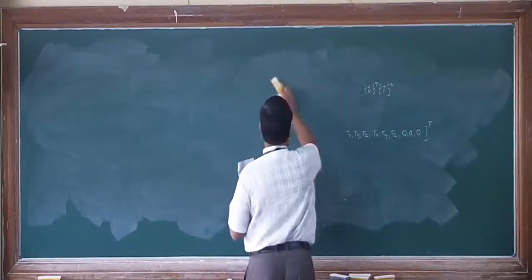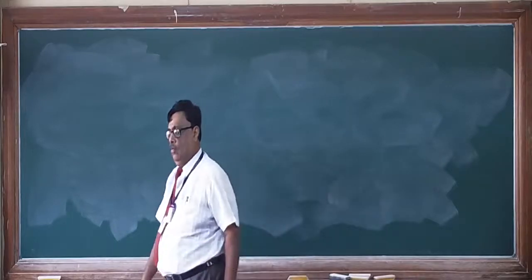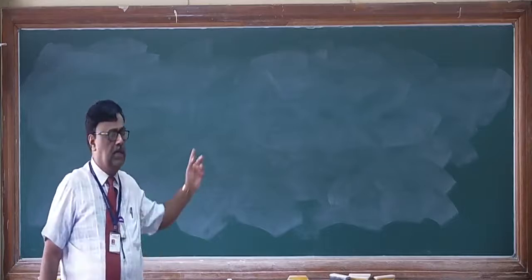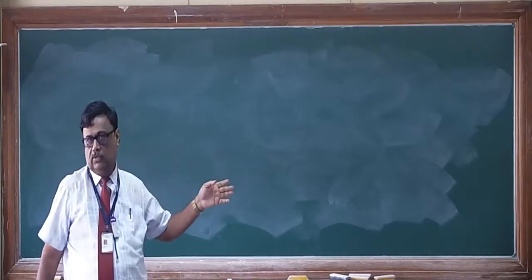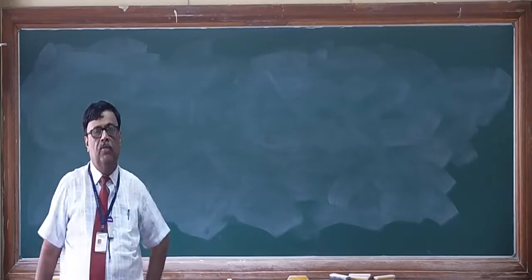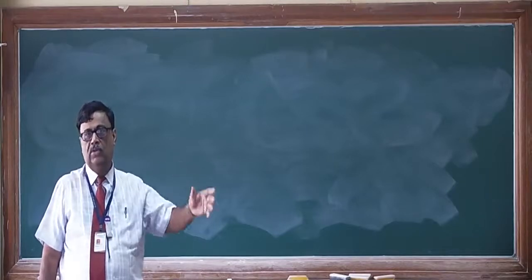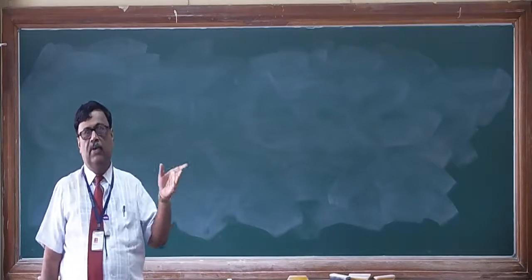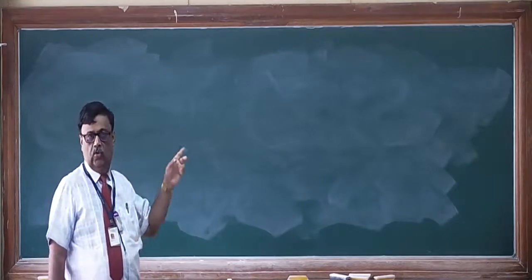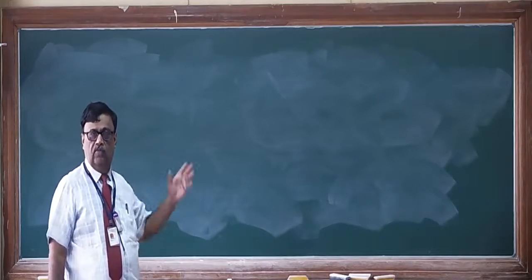Once you have formulated the element stiffness matrix, and you have written it for all the elements, then you go for the global stiffness matrix by taking into account all these forces. Of course, the point force will remain the same. Wherever the nodes at which the point load is acting, they are all summed up with the corresponding displacements. So that's why Ui transpose Pi, you will get that. Depending upon which components of forces, X or Y or Z, Px, Py, Pz, these are the 3 components of forces which are acting at a node. If you multiply by U into Px, V into Py, W into Pz, then that will give you the total summation of the influence of the point load.